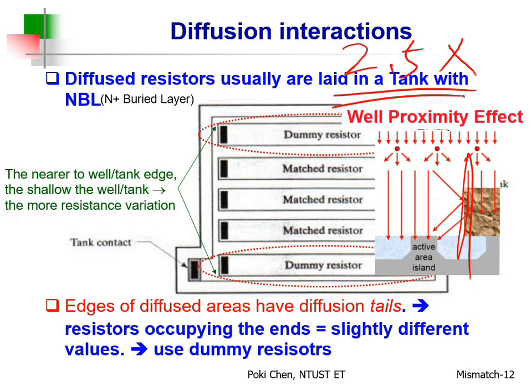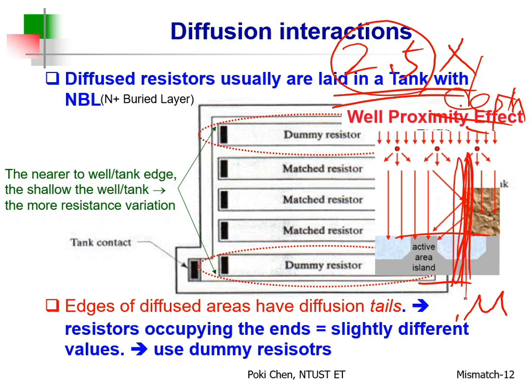This is what is recommended by TSMC. 2.5. Okay. Compared to what? Depth. The depth of the well, right? You need to keep 2.5 times the depth away. That's it. For example, if the depth of the well is 1 micron, then it means what? You need to keep 2.5 microns far away from the boundary. Got it? That is the fundamental requirement.